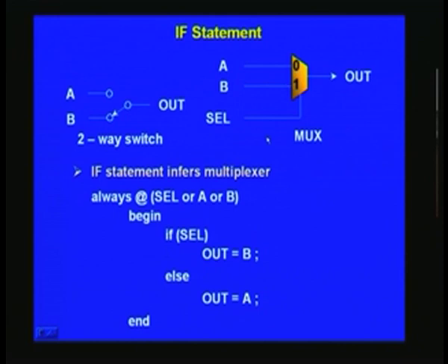So, what should you have? Select must be 1 here, then only this B is selected. That is precisely what this statement means. If select is, if you do not put equal to 1, which you can also do, it implies that it is 1. So, that is a short notation, but I personally discourage this. You put double equal to, then 1 tick b1, that will convey how many bits and all at one stroke.